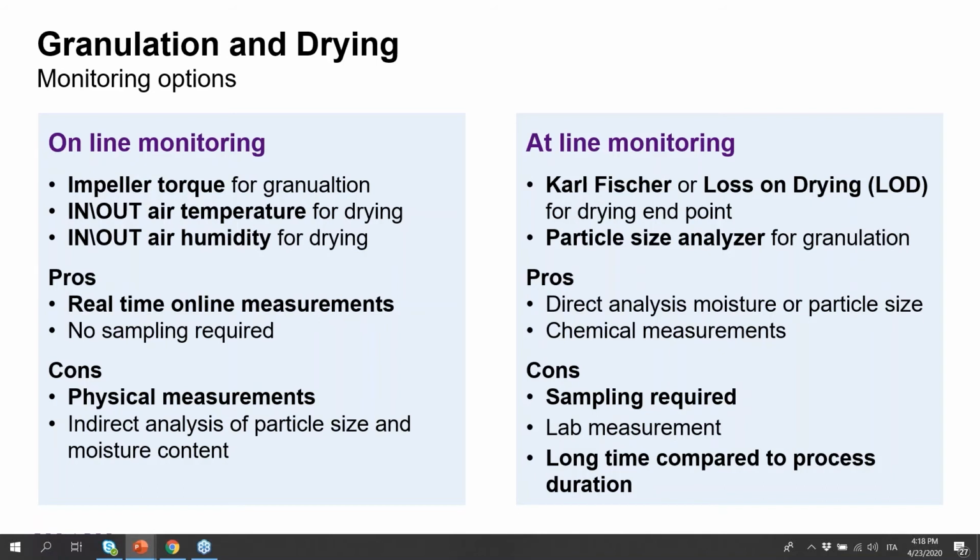We go to the laboratory, and there is a long time to get an analysis compared to the process. Let's assume that the drying process is 20 minutes globally. To do a Karl Fischer when the moisture is like 10%, it probably takes 5 minutes, meaning that even if you are super organized, you can do maximum 4 samples, ignoring completely what is going on in between.